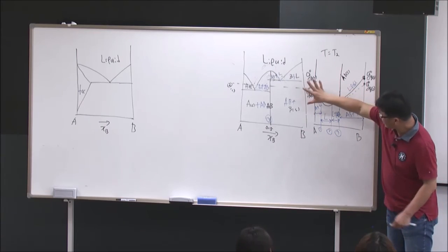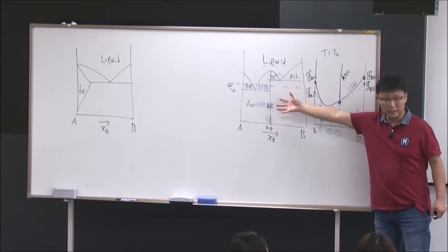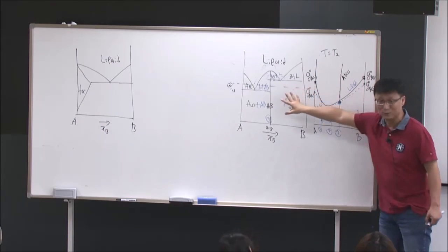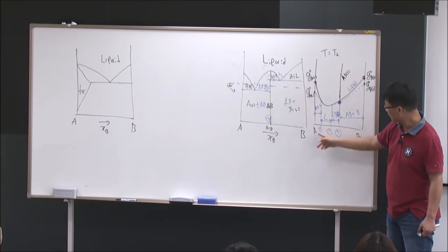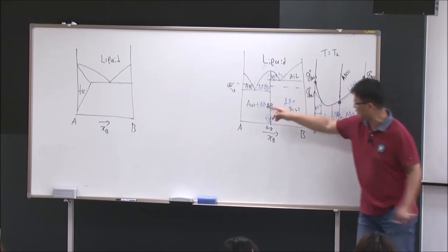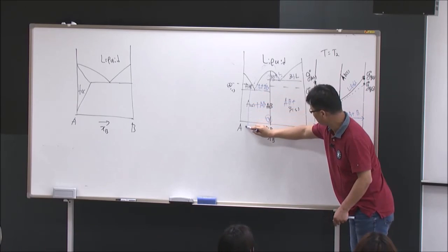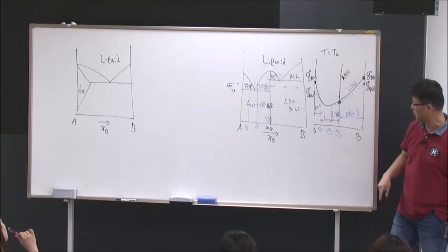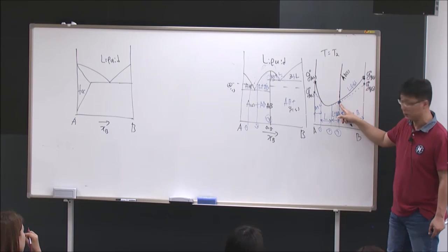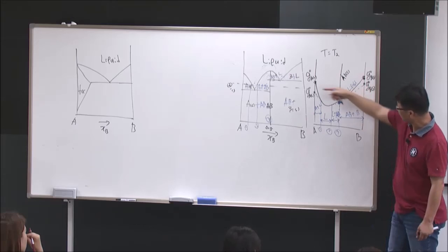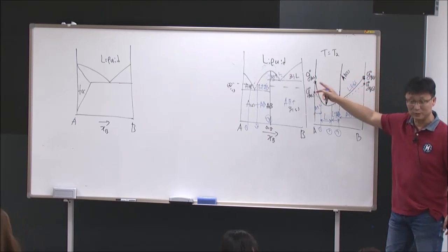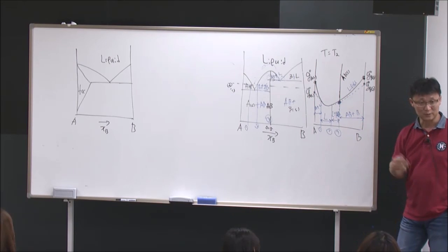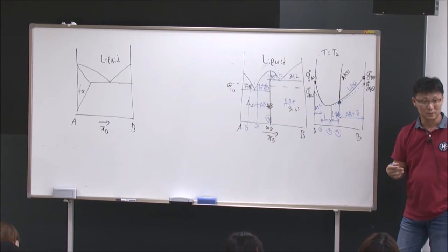So in this case, you know the phase diagram, so you have to really make your diagram based on the phase diagram instead of making this one to compare it. It's very difficult. So you just draw it. Okay, where's the 1, 2, 3 composition? This is basically composition 1. This is composition 2. Composition 3. You know reasonably where it should be. And then you just put your AB point, and then the A point and the B point, and then draw the liquidus line in the middle by yourself to make two common tangent lines inside here. That's the easiest way. Okay?